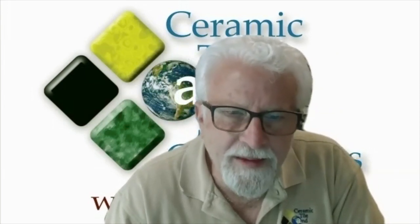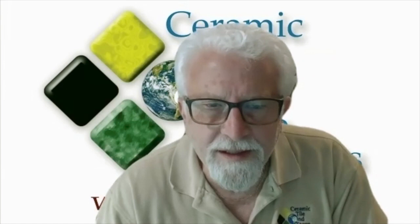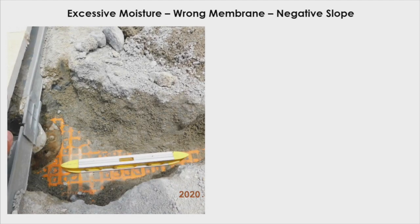Now, it also acts as a moisture barrier, so it doesn't allow any moisture from the mortar bed to get away. And plus, Ditra doesn't recommend this as a waterproof membrane. It actually needs an additional waterproof membrane to perform correctly. But anyway, it should have never been used in this application.